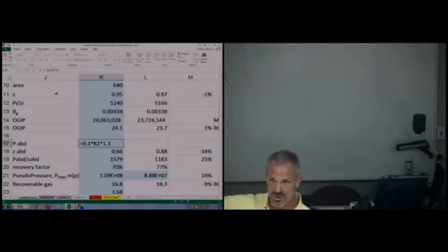And then also those very high ends that are rolling off the stock tank oil to the atmosphere, we call them tank vapors. They're a high gravity. They're a lot different gravity than the separator. We have to account for those also in determining the well stream gas gravity that came up the well.